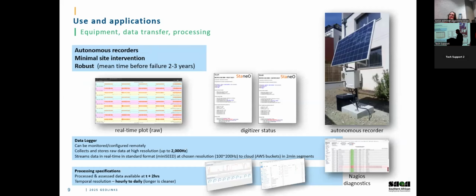The equipment looks like this. Top right picture, it's a digitizer in this gray box. Actually, there's 3 in there, and a cellular data modem, an external lead acid battery, which is charged by a nice big solar panel. That thing will just keep running by itself. This one, I think, is a microseismic station. There's only one cable going in there, but we have 27 channels in our version, so we can support 9 3-channel sensors with it, which, depending on the station spacing you pick, we can cover about 1 kilometer along a wall with one of those.